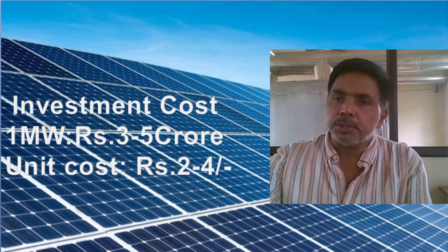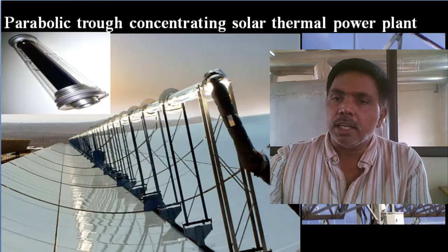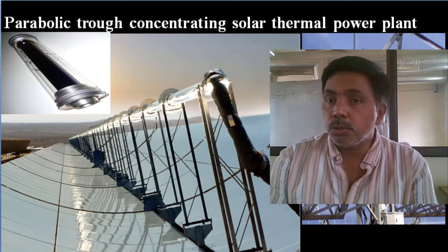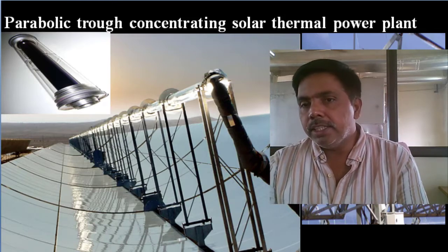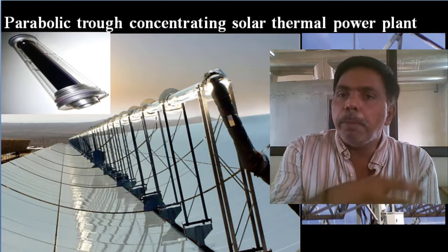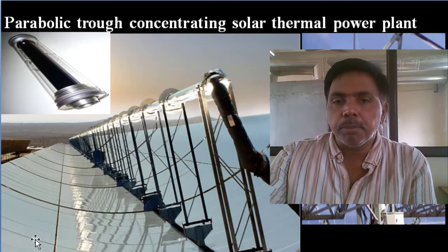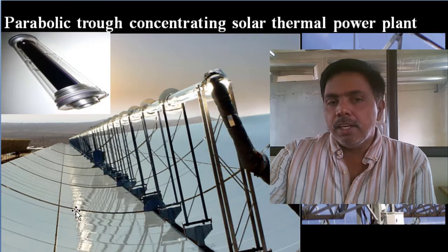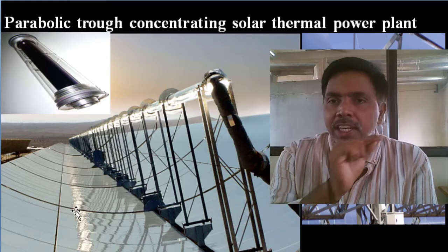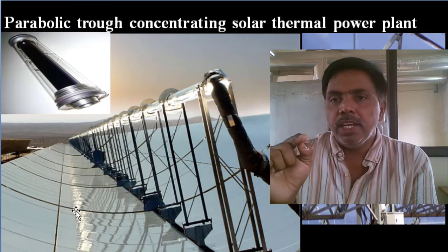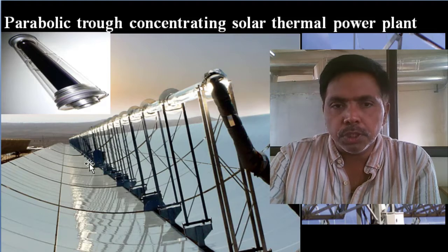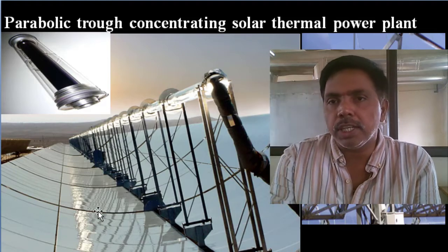Next, other options we will see, because these are all harvesting options. Next, solar concentrated systems, solar thermal power plants. Here, the first concentrator is a line contact concentrator, the parabolic trough. You can see this is the parabolic trough. One trough, one collector. Whenever we call one collector, it contains 12 modules like this: 1, 2, 3, 4, up to 12 modules called one collector.